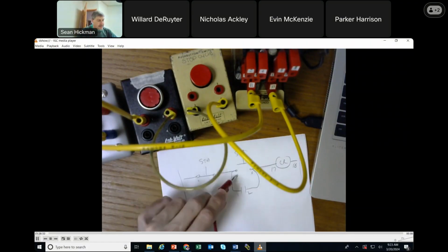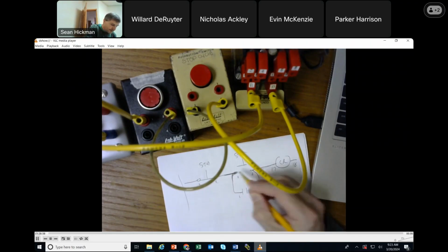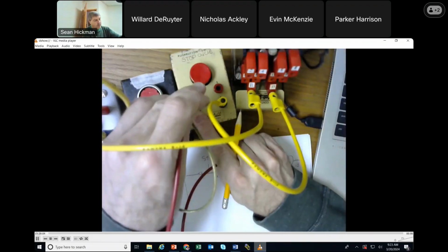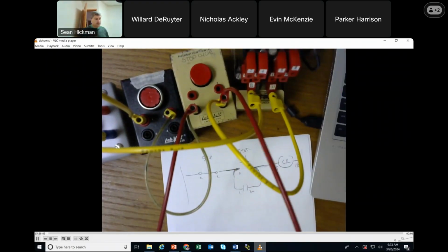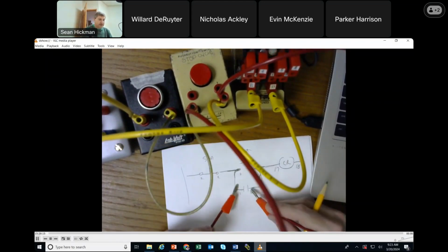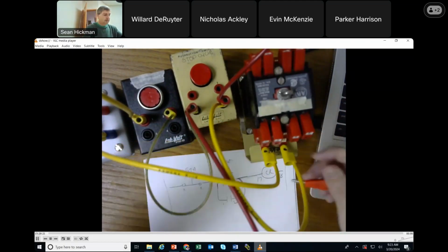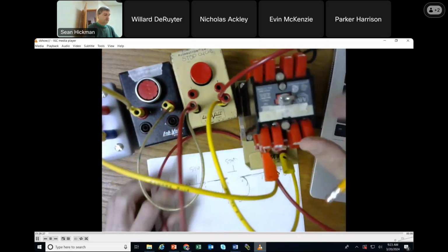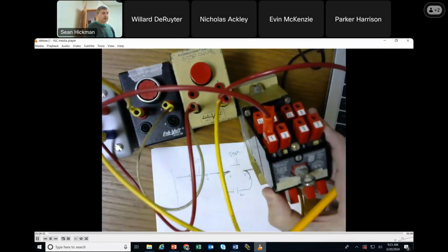So I'm going to use red so that you can see the stack. So I need a contact stacked right here on the start, because this start has 1 wire, 2 wires coming off of it, and this side has 1 wire, 2 wires. So here's the first wire, here's the second wire. Same on this side. Here's the first wire, here's the second wire. So now I've got 2 wires coming off of there. And it says they go to 1 and 2. Where's 1 and 2? It's up here. So here's 2. Right there, it's 2. And here's 1. Right there. Okay? So now what happens?